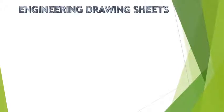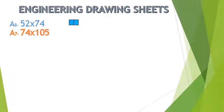Engineering drawing sheets. Now we will discuss the size of some common engineering drawing sheets used. First we will have A8 with size 52 mm by 74 mm. Now we can see on the screen we have two A8 sizes which combine to form A7 size, that is 74 by 105, and two A7 combine to form A6 with size 105 by 148.